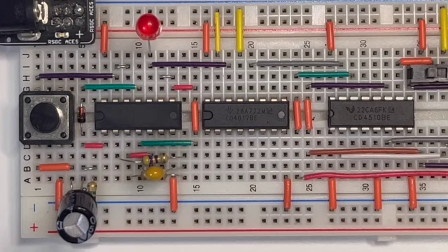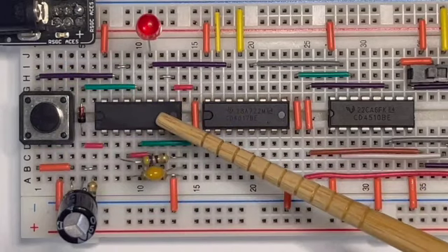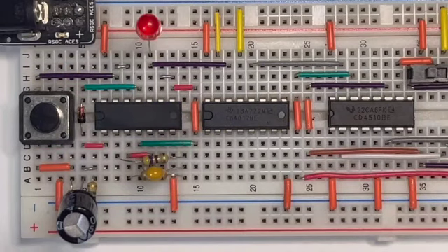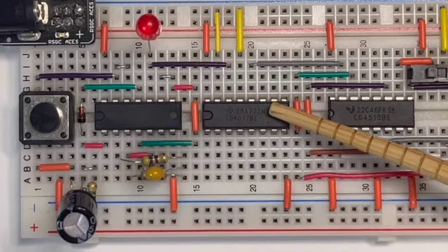Part 3, the 4017 decade counter. The 4017 decade counter is a specialty chip that can be used to count how many oscillations are being produced per press from the NAND gate oscillator. Though in this particular circuit, we're using it solely for the purpose of slowing the oscillation of this NAND gate oscillator down by 10 times.